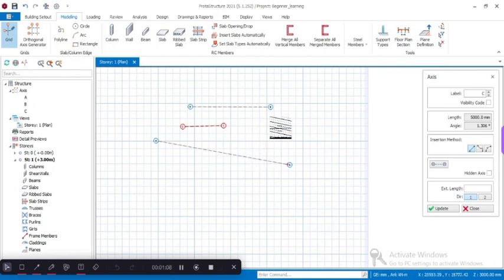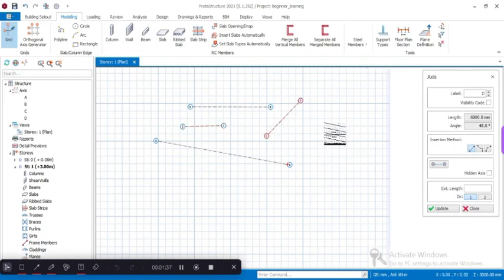What that means is, okay, this line, this is the delta x. You can see the delta x there, the delta y, and then you can see the length and angle. So we can use those notations also. So let's use the example they put there with Shift F2, and they use 6,000 at 45 degrees. You see how it went. That's it.